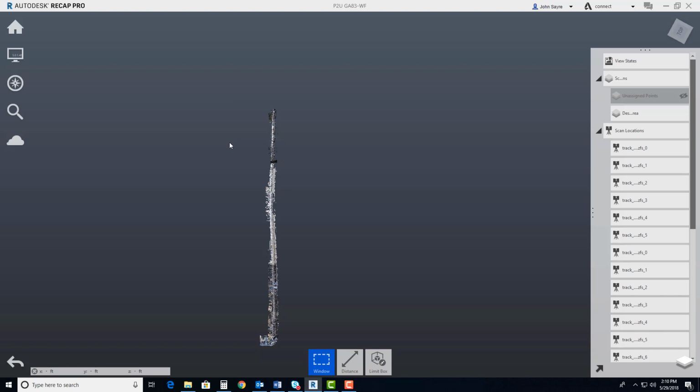You could either bring in the entire point cloud and generate a surface from the entire point cloud, or if you only have one area like I'm showing here, you could just bring in this point cloud and it'll keep your model from getting too large. That doesn't mean you can't generate a surface from the entire point cloud, because you can. I just wanted to chop out a piece of the point cloud so that we could create linear features and things of that nature on just this one area.